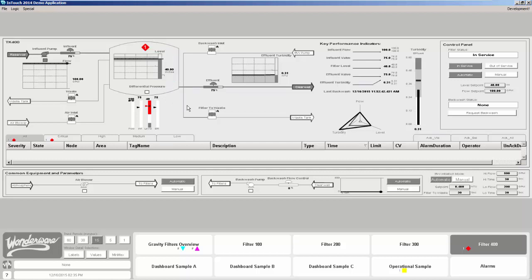So that's the essence of what the alarm border animation is. In a high-performance HMI, situation awareness type graphics, draw the operator's attention to things he needs to look at beyond just looking at the numbers and the variables on the screen.